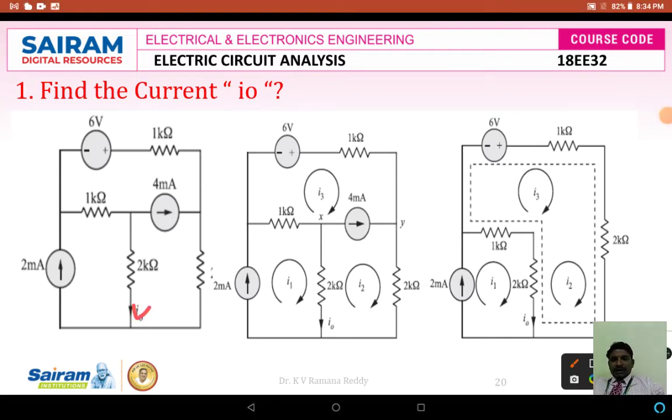This current I naught I want to find by applying the super mesh analysis, because it is not possible to use mesh analysis, because in this problem there is a 4 milliamperes current source which was located between the boundaries of this mesh and this mesh. So I want to apply the super mesh analysis technique here.